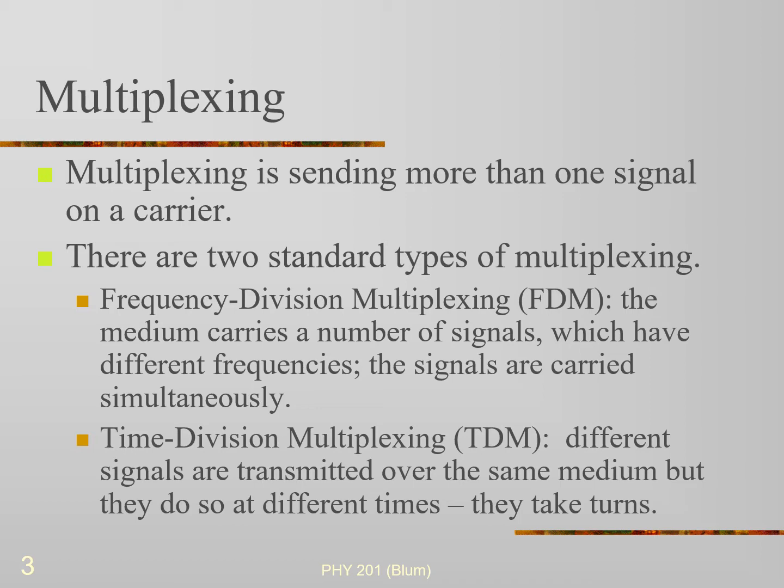So the information is sent out by many radio stations, and then the receivers can listen to those radio stations by tuning in. They are picking out the frequencies at which the signals are sent. And so that's why it's called frequency division. The organization of the signals so they don't interfere is done by giving them different frequencies.